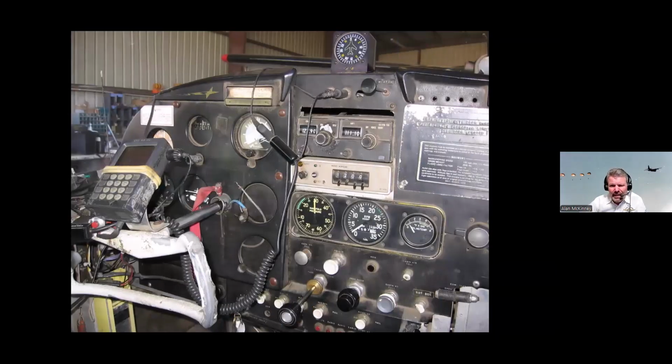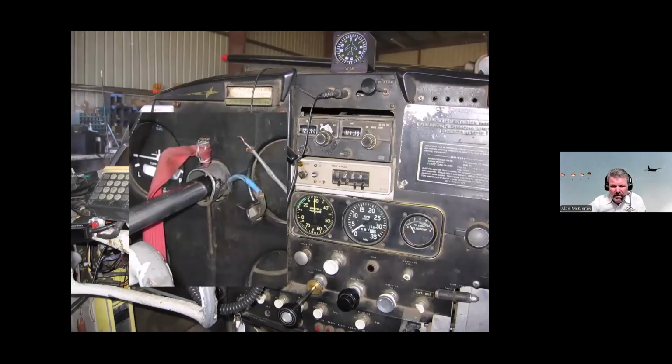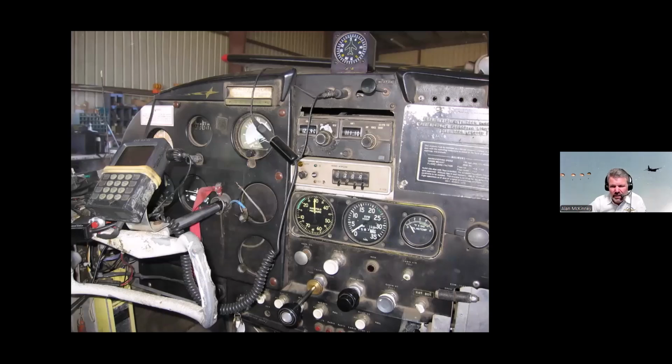If the cockpit looks like this, be aware, because obviously that's missing. That lock, is that really correct? It doesn't mean it doesn't work, but again, it's going to give you some insight, not to mention the bare wires next to it. Yeah, knob's broken, more broken. Yeah, wrong hardware. Someone mounted something to a yoke. Look, anytime you mount something to a flight control or a seat or a berth, think STC, because it's a flight control. And is it in the way? It's just hokey.